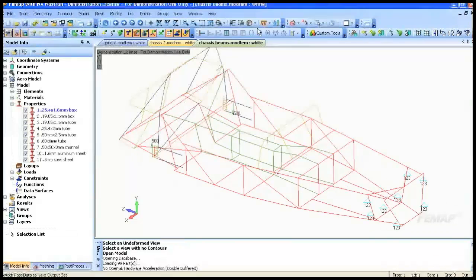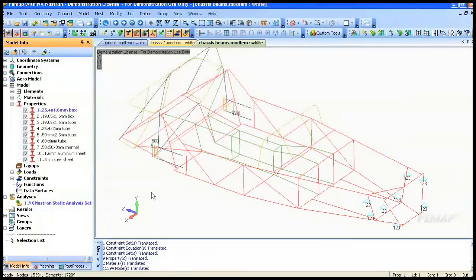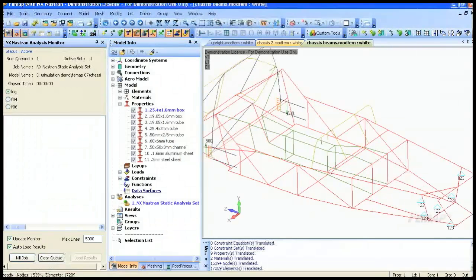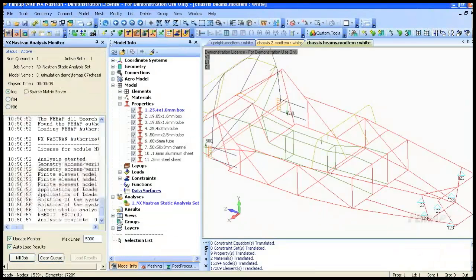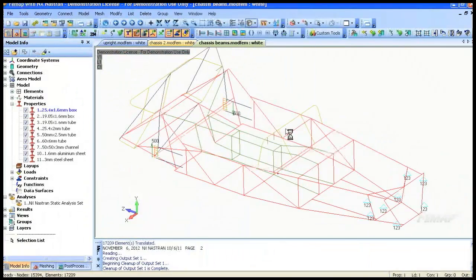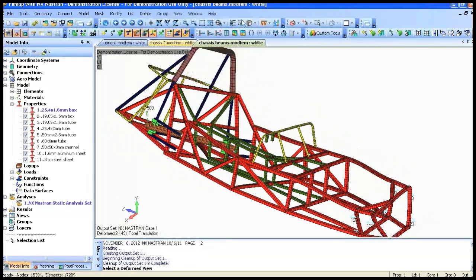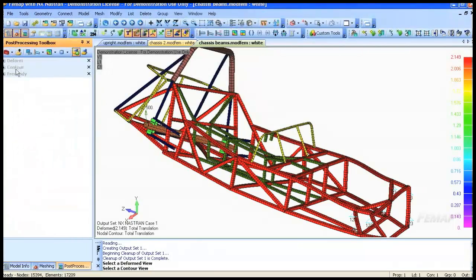Two forces on the back, and then we're going to look at the displacement of it to give us an idea of the rigidity. The model's already set up, so all we're going to do is run it. One very nice thing about beam element models is they run extremely quickly, because we've only got 15,000 nodes in this model compared to nearly 10 times as many in the shell model. So that's run. If I put the thickness section on again and plot, and maybe look at a displacement as well.